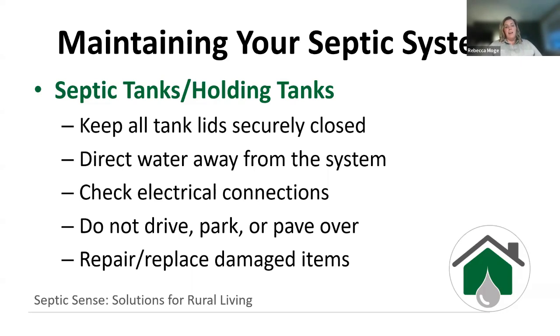We don't want to drive or park on our septic field or our system. That not only compacts the soil, but it breaks the laterals and things that are underneath it as well. So we want to make sure that the septic system is in a place where we're not driving over it.